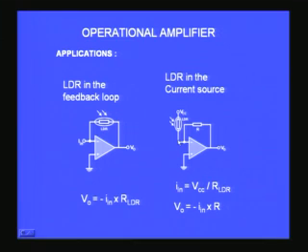So we can try to apply a voltage to an LDR in dark, so that the resistance is high, voltage can be anything, and because of the large resistance of the LDR you get a almost good current source. So that is what is exploited here.